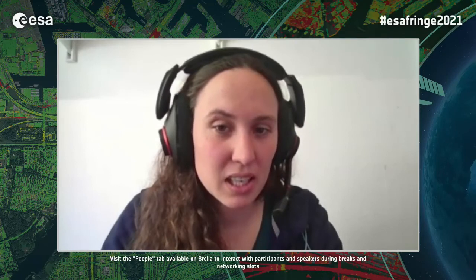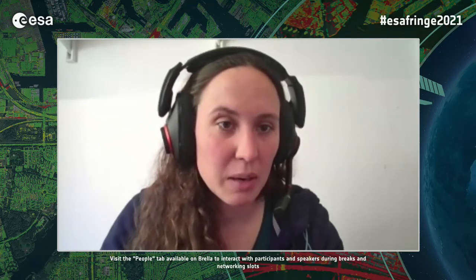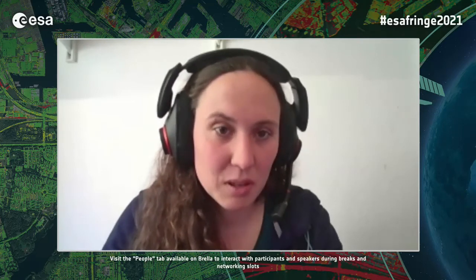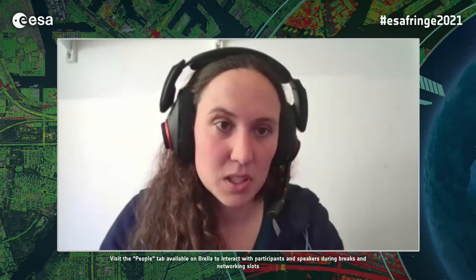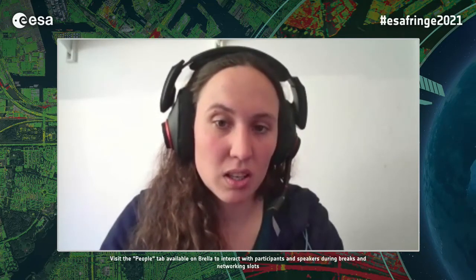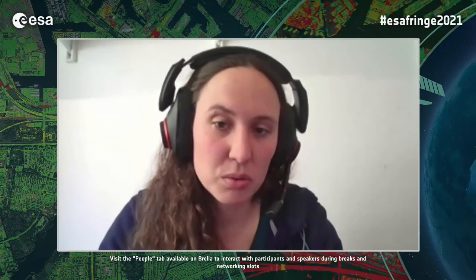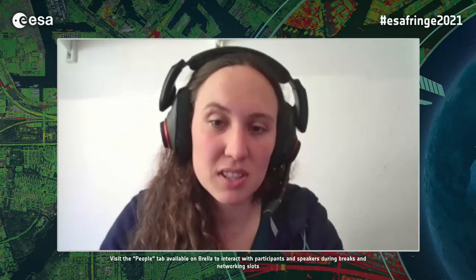Yeah. Thanks. There's also a second question, I guess, still for you. Can you see it? Yeah. Shouldn't we model delay due to pressure differences and not only use zenith wet delay? Yes, that would also be an idea, but the pressure is directly in my calculation of the zenith wet delay. So all the pressure differences I have from my ERA5 model, and they are also in the zenith wet delay. So I think the model should include the pressure differences. Yeah, thanks.